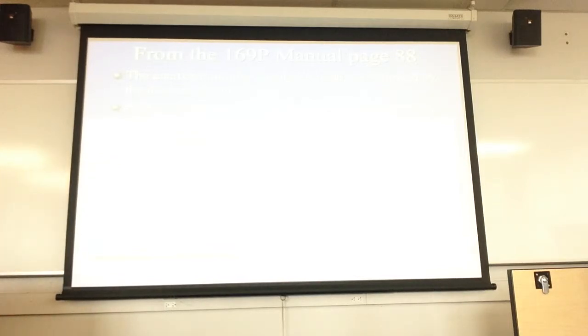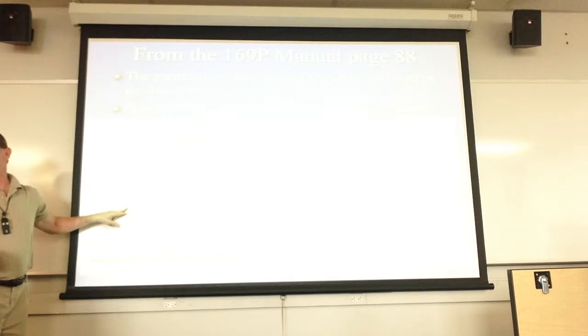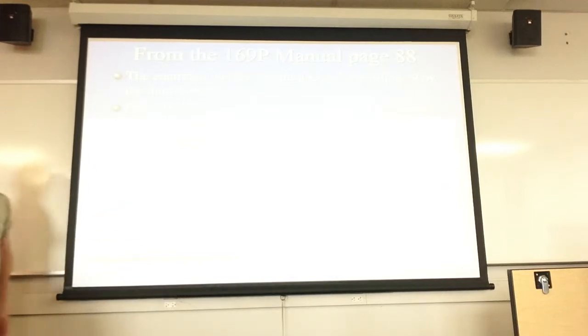Let's say we knew that we had a specific element connected to port B, could we rename it to be something that we wanted it to be, like LED port or something like that? No. These are very specific. DDRB, pin B. You can't call it LED pin B. It's not going to happen.